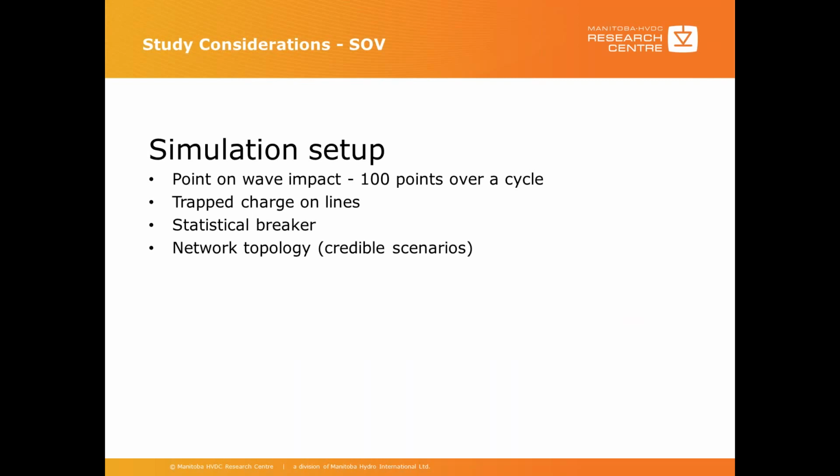Once the model is validated, you can set up the simulation for the switching study. The switching overvoltage magnitude is primarily dependent upon the statistical variation in the point on the voltage waveform at the instant when the current arc is established between the various breaker poles. In order to capture the point-on-wave impact, each simulation scenario can be run 100 times or more if needed over multiple simulation runs. The breaker closing sequence is then determined by randomly generated pole closing times using the statistical breaker model available in PSCAD.